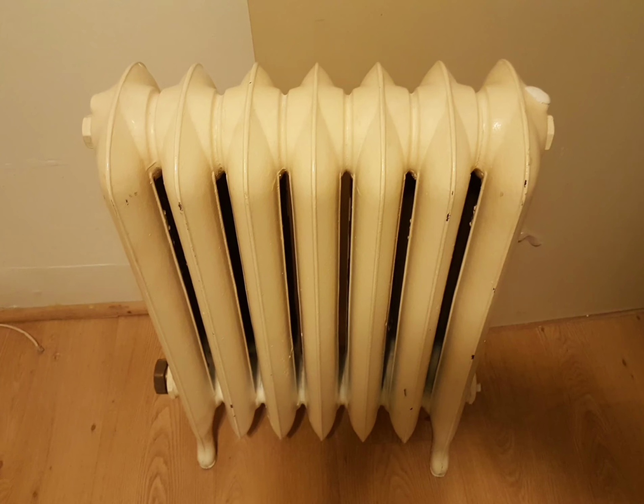But the reason I bring that up is, with this particular radiator, steam would get into your service valve, and instead of making its way to the top, it's going to make its way all the way to the back of the radiator. The first thing it's gunning for is the air valve. Excuse me, not the service valve, I'm sorry, I'm confusing people. The air valve. So the steam comes into the service valve, makes its way through the lower portion of the radiator, and goes all the way to the air vent and locks out.